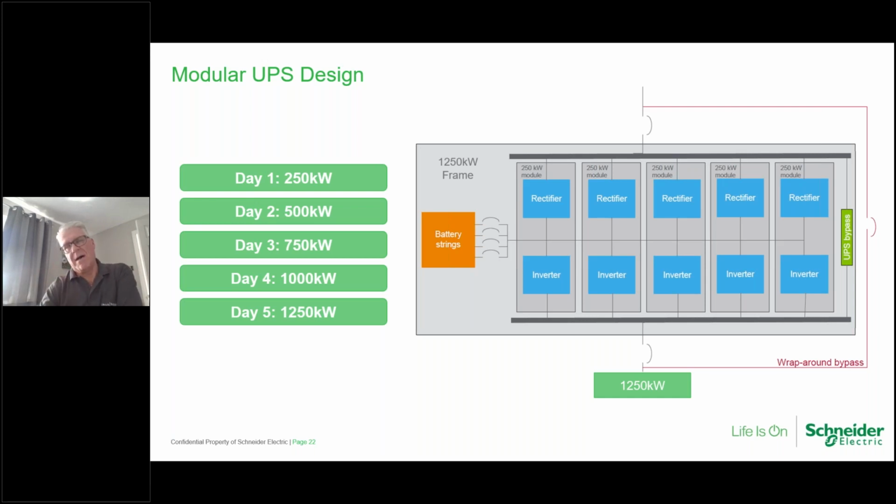And some of the more up-to-date UPSs are available with live swap of the power modules. So if you have an issue with the power module within the frame, a trained operative can change that module themselves, which obviously reduces your mean time to recovery of a system.